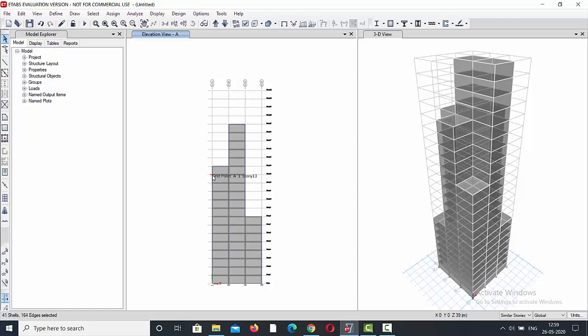So in this category you can see that in the windward direction you have wind pressure coefficient as 0.8, and at B direction you have wind pressure coefficient as minus 0.25, and in directions C and D you can see wind pressure coefficient as minus 0.8. So what we need to do is, the section A here will have wind pressure coefficient of 0.8.